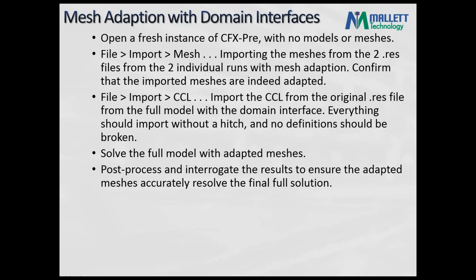Next slide. Then you're going to open a fresh instance of CFX-Pre, no models or meshes, and you're going to just import the meshes from the two results files that you created. Those will contain the adaptations to the mesh in them. And then finally, you're going to import the CCL from the original coarse model. That contains the domain interface and all the original boundary conditions. Resolve that full model with the adaptive meshes and post-process on it to make sure that the adapted meshes accurately resolve the full final solution.